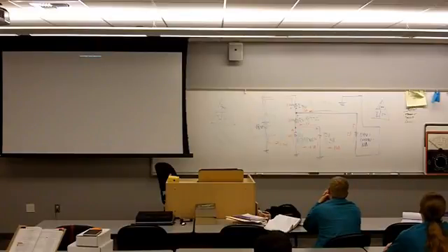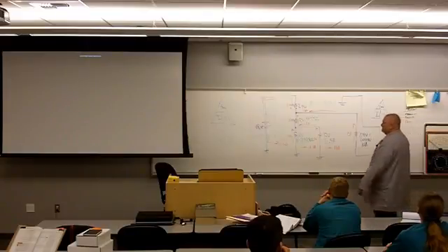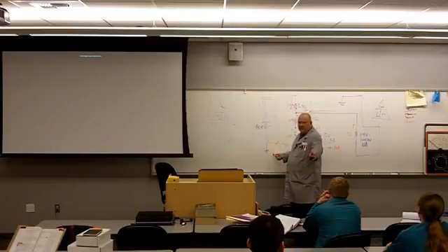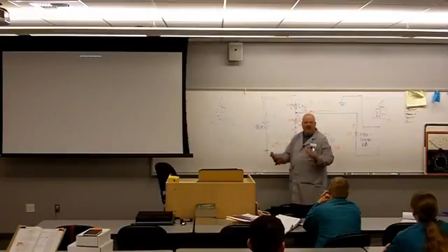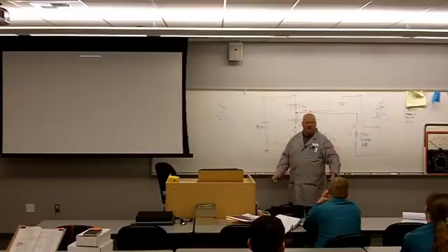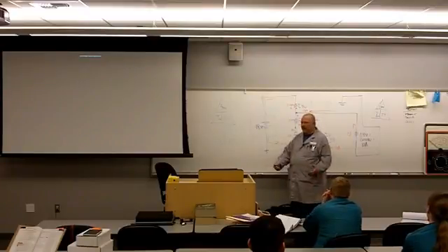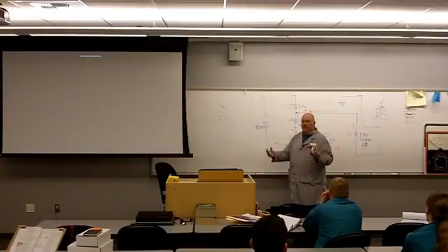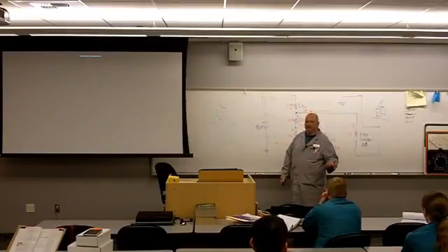What is it? It's the exact same circuit. And to be honest with you, this is how this thing would really be connected. Your 48 volt power supply would be connected to what kind of ground? Electrical ground. Not necessarily earth ground, electrical ground, which is typically a chassis ground or the frame of a vehicle or a boat, the hull of a ship, right? The frame of a train car. This is how it's going to be done, because we're going to use the frame as a conductor.